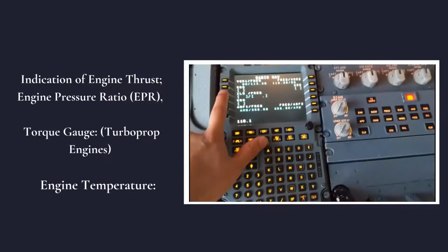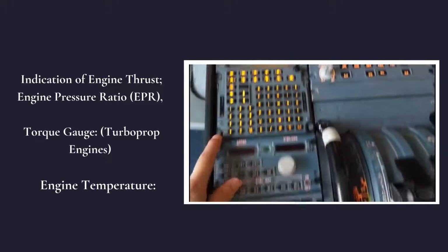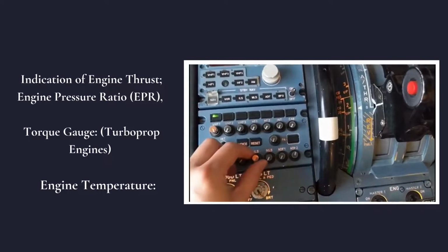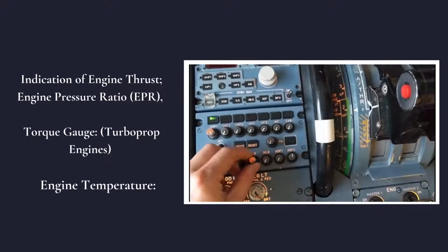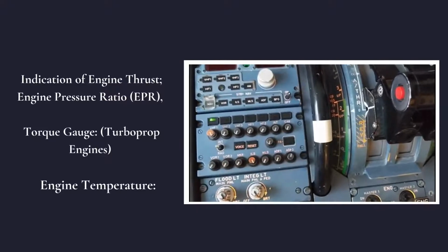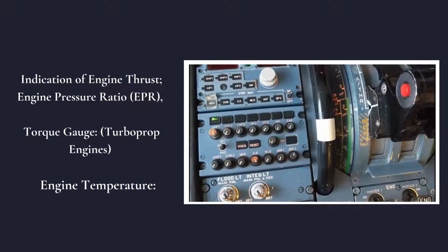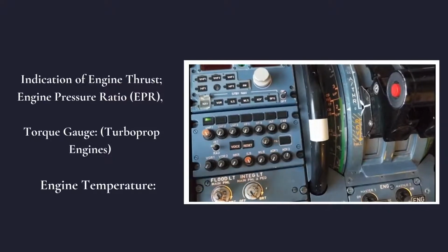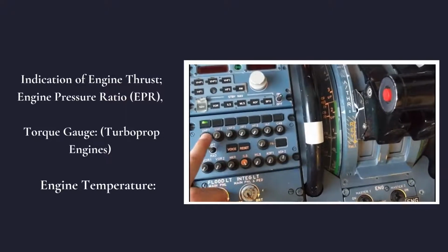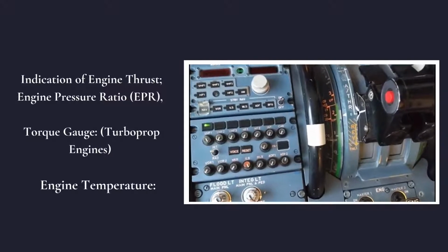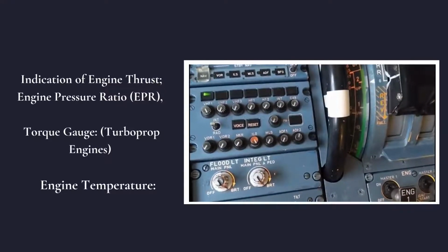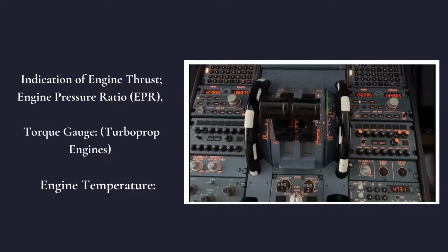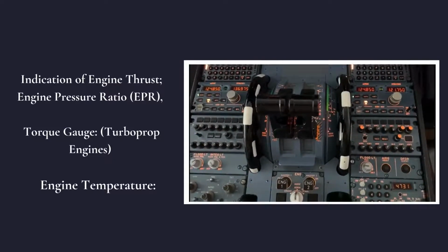In most systems, the torque gauge oil pressure is used to actuate a torque gauge oil pressure gauge instrument proportional to the engine power in pounds per square inch. Some torque gauges are calibrated to be read in the terms pound-feet of torque, and some can be read in shaft horsepower directly.